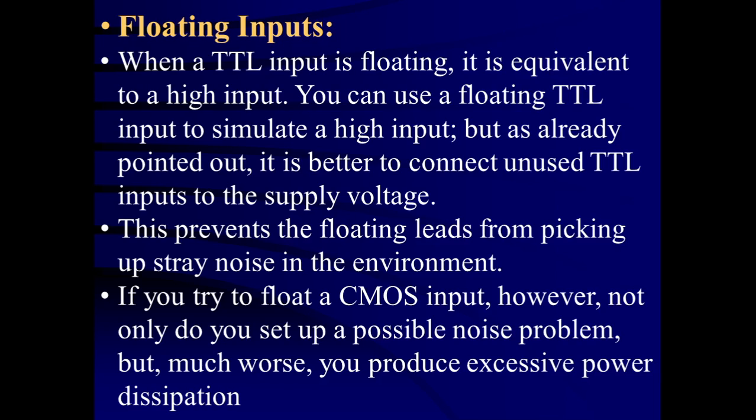So in case of the TTL, if the unused input is floating, it is equivalent to a high input. So if you are not utilizing the unused input, you can keep it floating and it will act like a high input and it will not affect the rest of the inputs controlling the gate.